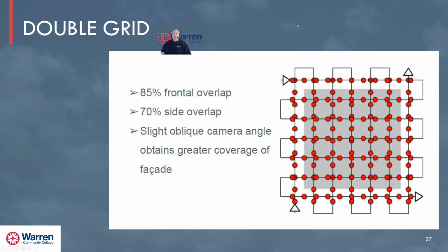Now, there's another option when you're picking in PIX4D Capture, and that's called the double grid. And you can choose, and this is going to give you, as I'm going to show you in a second, more accurate results, but it's more to process as well. And that's kind of the trade-off in this decision-making process from your standpoint. That's where your skill set comes in.